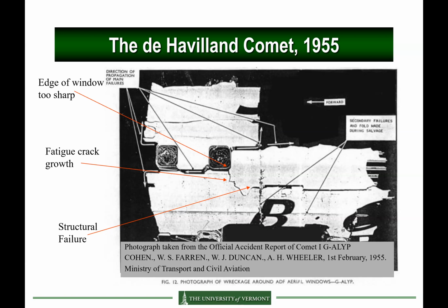followed by fatigue crack. So it's zigzagging downward here. And then when the crack became long enough, you see this flat and straight horizontal crack, which is the portion of the crack under catastrophic failure. So if you want, the initiation of the crack was very slow. The fatigue crack growth was a bit faster, but still slow. And then the structural failure was extremely fast. Okay.